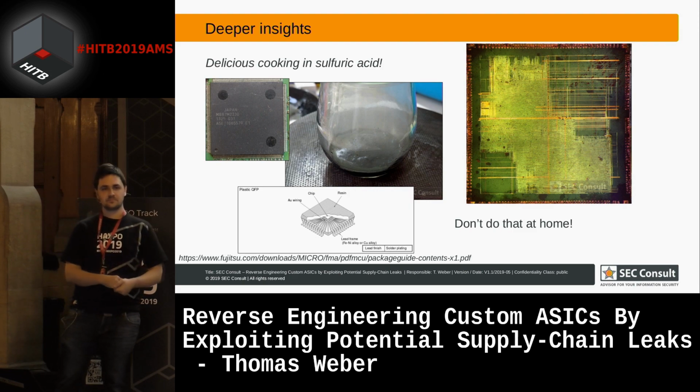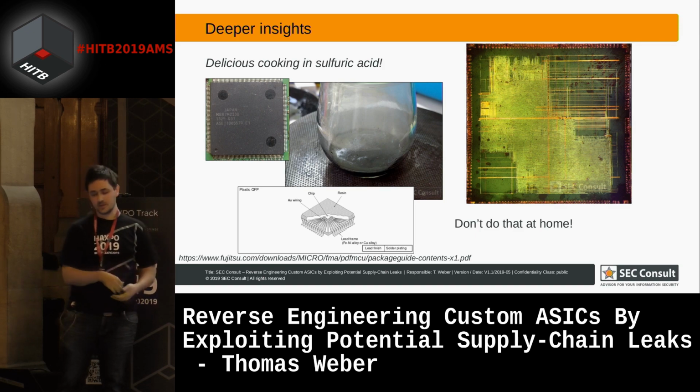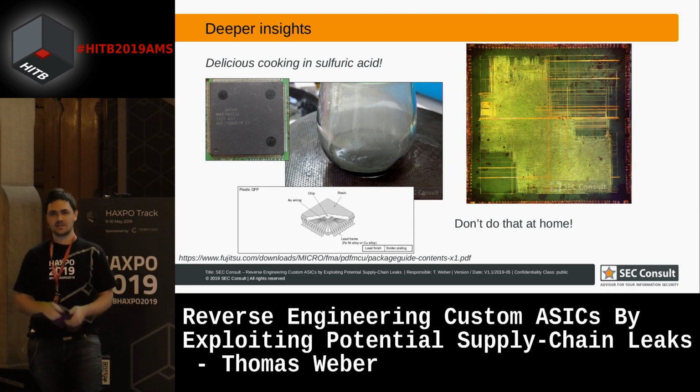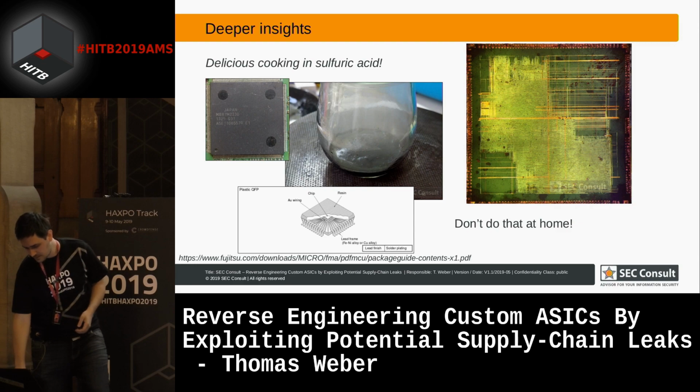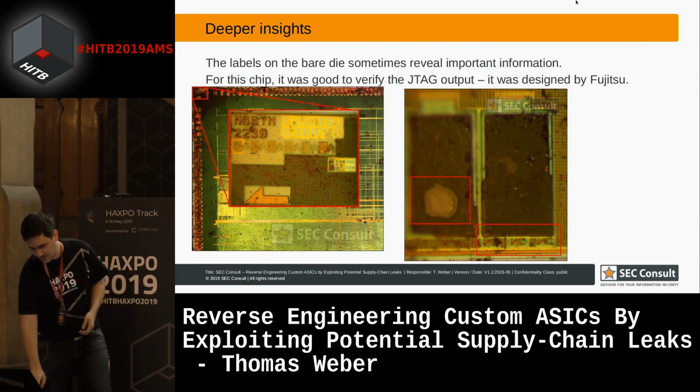For decapping the chips, because there is just the label Japan and some number, I used sulfuric acid. It smells not so good, so be careful and don't do it at home. But you get beautiful pictures with a confocal microscope, and you can also read some labels. And in that case, it was designed by Fujitsu.